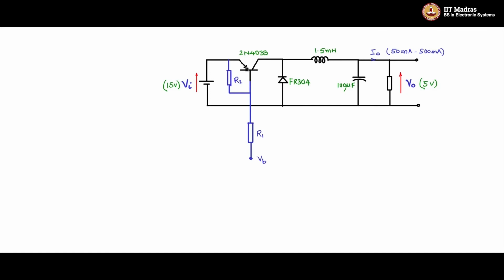And then at what frequency do you switch this BJT? So let us put that down. Switching frequency of the BJT, 20 kilohertz. So almost everything is ready except that we need to give the pulse width modulated waveform here at VB. So we had looked at how to generate pulse width modulated waveform some time back, and I had also told you that there are commercial ICs available.